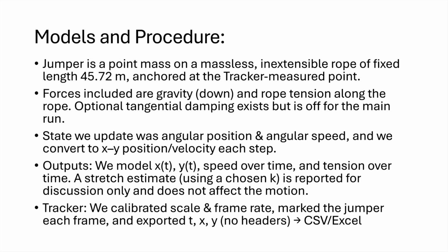Forces included are gravity down and rope tension along the rope. Optional tangential damping exists, but is off for the main run. The state we update is angular position and angular speed, and we convert to xy position and velocity each step. Outputs we model: xy speed over time and tension over time. A stretch estimate using a chosen k is reported for discussion only and does not affect the motion.